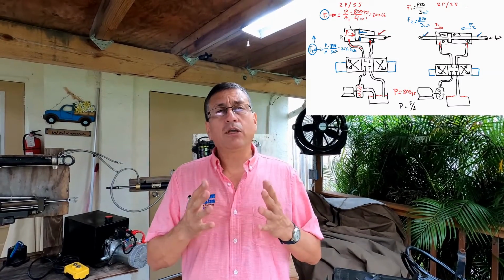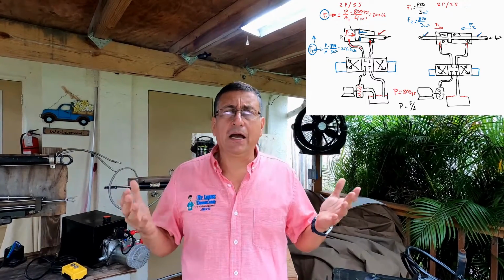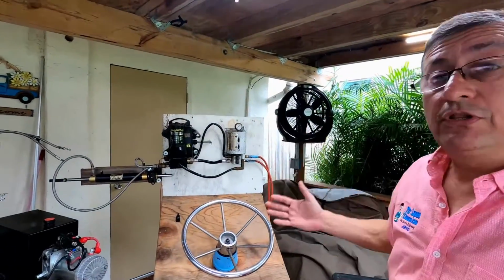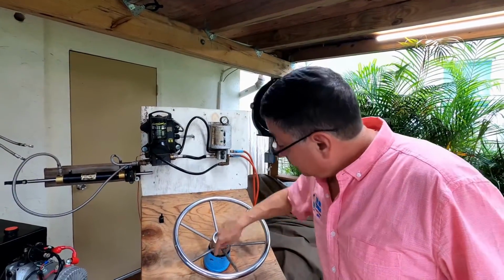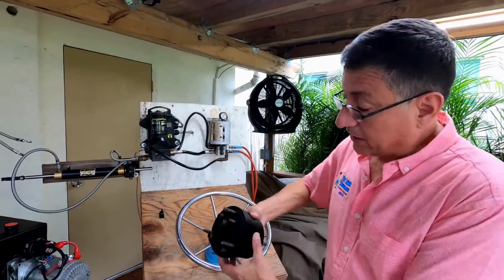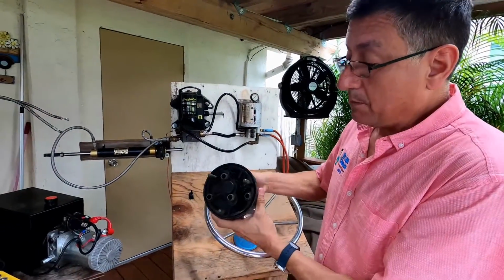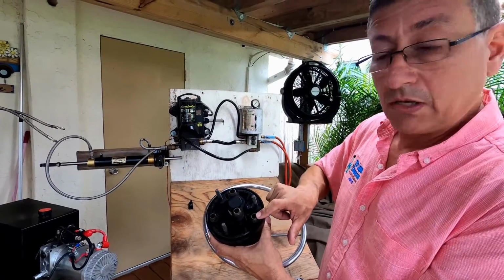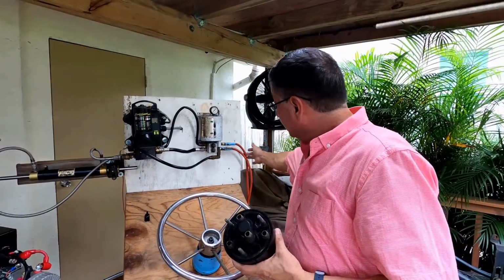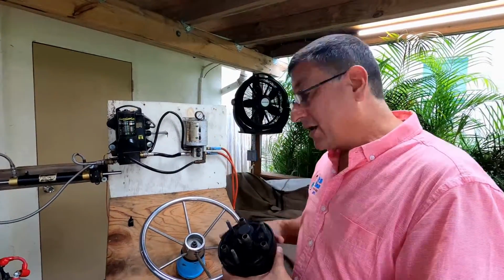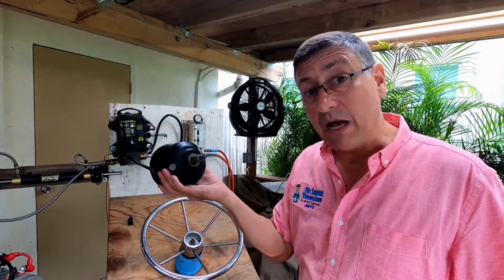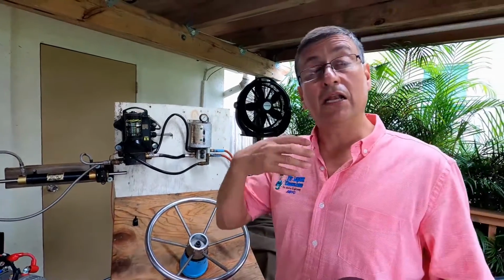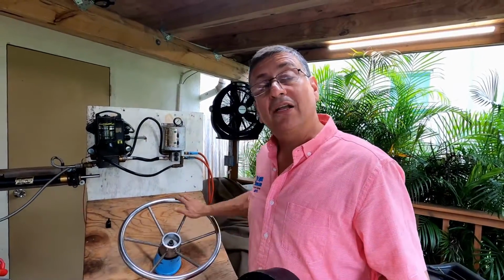Okay, we are going to quickly refresh the typical hydraulic system. Remember, in a typical hydraulic system, for example, this is the steering system. We have the pump. Remember that in this particular case, the pump is a mechanical pump, the hand pump. The fluid is going to the starboard side, port side, and this is the return. The fluid enters from port side, starboard side, into the reservoir. In this particular case the pump is manual, because I move the pump with my hands. It's a hydraulic pump, manually activated.